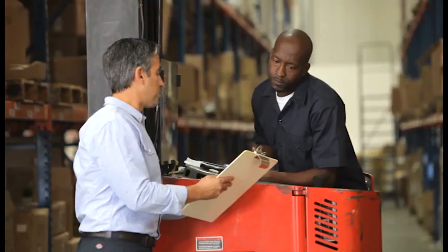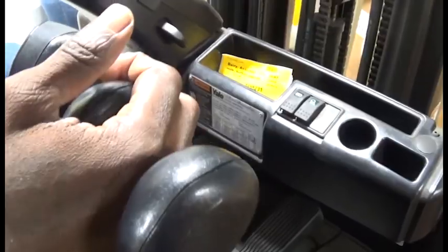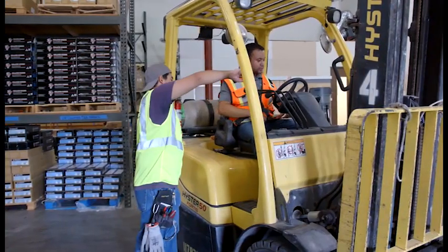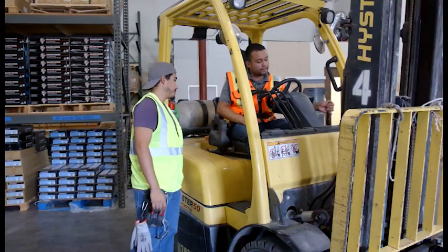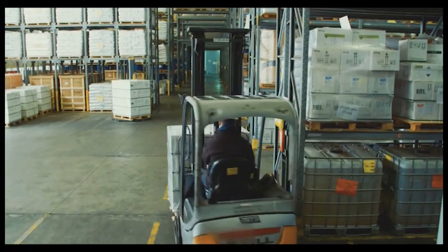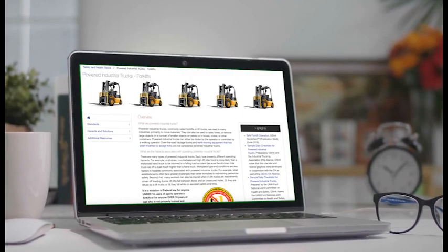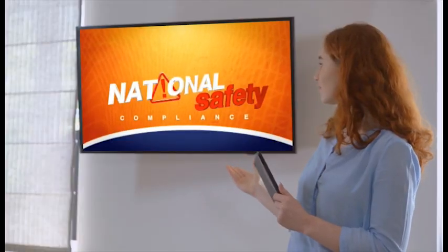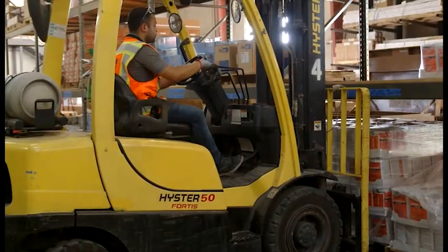Forklift operators must be trained and certified by their employer. Trained operators must know how to do the job properly and do it safely, as demonstrated by a workplace evaluation. Training should consist of a combination of formal instruction, practical training, and evaluation of the operator's performance in the workplace. Formal training consists of classroom-type lecture, discussion, interactive computer learning, video, and written material. Practical training includes demonstrations performed by the trainer and practical exercises performed by the trainee.